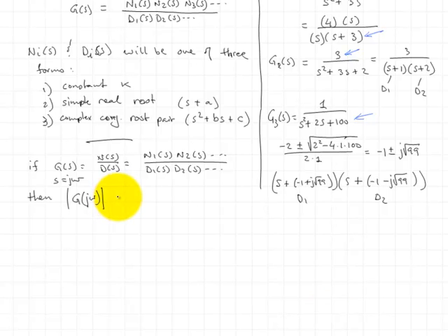So I'm going to claim that the magnitude of the overall transfer function is equal to the magnitude of n of j omega divided by the magnitude of d of j omega. And furthermore, I'm going to claim that this is equal to the magnitude of n1 of j omega, I'll leave off the j omega here but it's implied, times the magnitude of n2 of j omega times however many subterms and subfactors I have, and then divided by the magnitude of d1 of j omega times d2 of j omega...